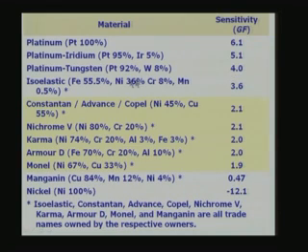And then you see here I have shown some with a yellow background. These are very common materials used in practice. Constantan is also given the name advance, some people call it copel. These are actually the names given by the manufacturers, and they consist essentially of a nickel 45%, copper 55% alloy, and the gauge factor you see is very close to 2, 2.1 here. Nichrome, nickel 80%, chromium 20%, it is called nichrome V, 2.1 again.